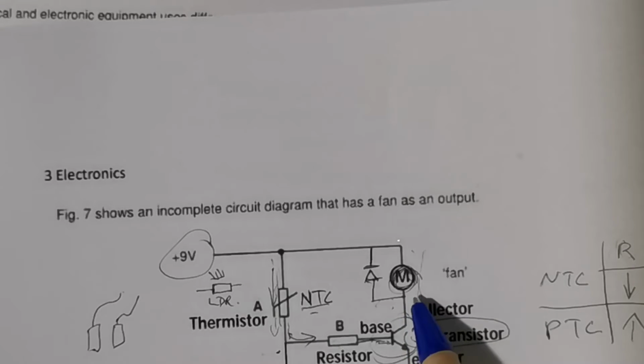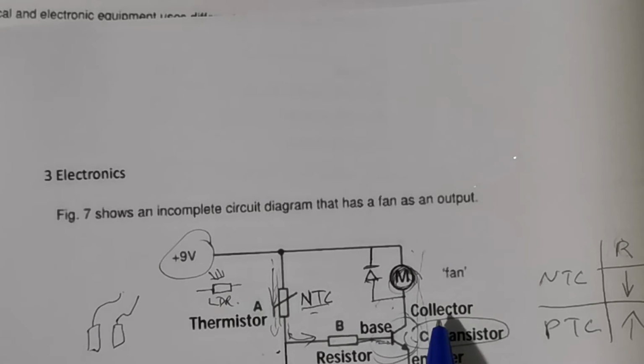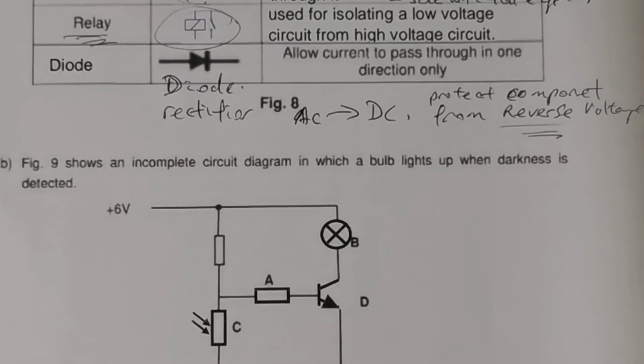A coil, that means what? Electromagnet. You need an electromagnet inside a relay. So you will need this protective diode. Refer to my deck of slides on relay, and they will explain a little bit more on that. So now there are two ways that the diode is being used.